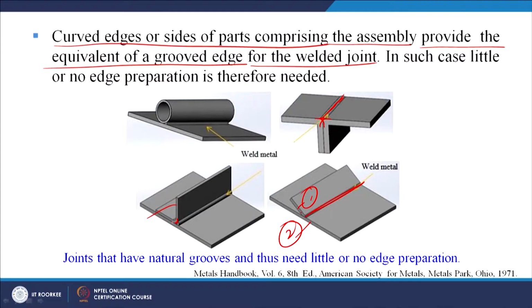So here also we can see this is round, so here we get a natural groove along which we can do the welding. So in such cases little or no edge preparation is needed or required.